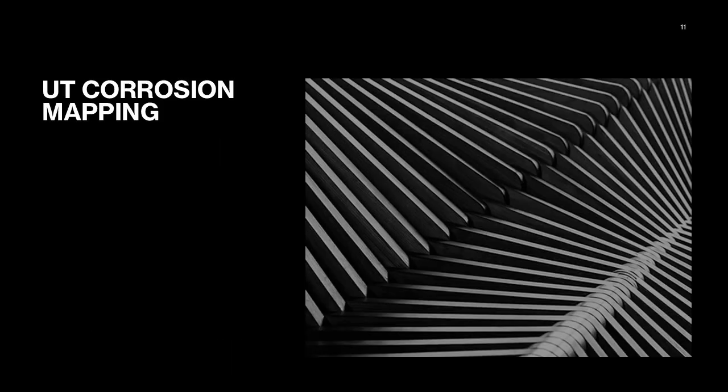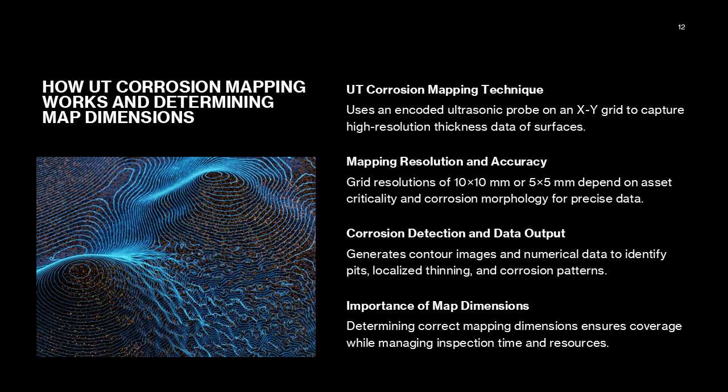How UT corrosion mapping works and determining map dimensions, why, when, and where UT corrosion mapping is used. UT corrosion mapping provides high-resolution, full-area thickness data by moving an encoded ultrasonic probe across a surface on a defined XY grid. Typical grid resolutions include 10 by 10 mm or 5 by 5 mm spacing, depending on the required accuracy, asset criticality, and corrosion morphology.